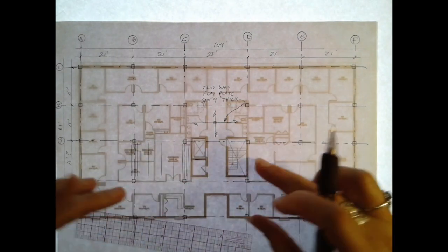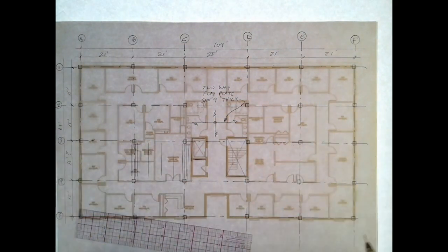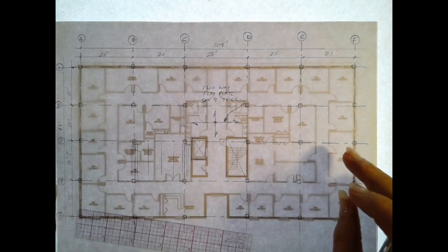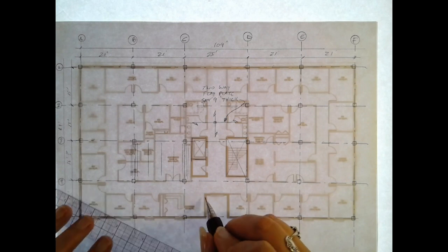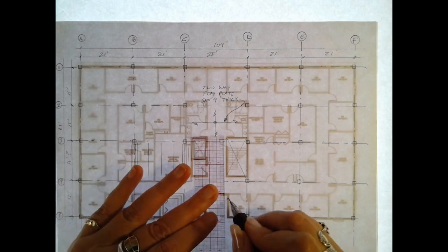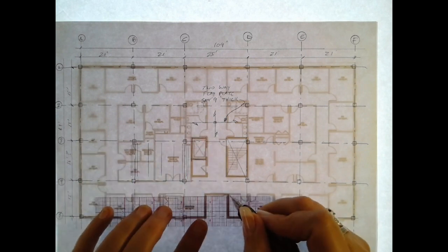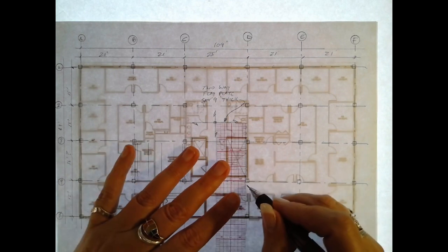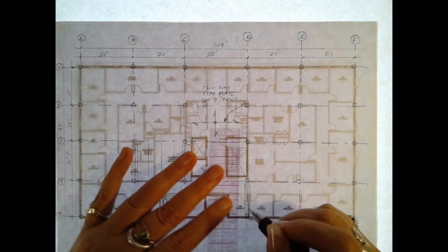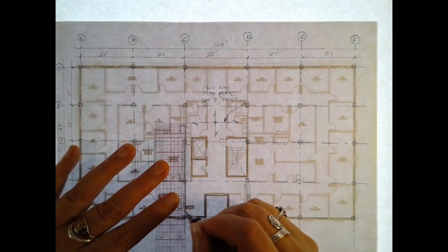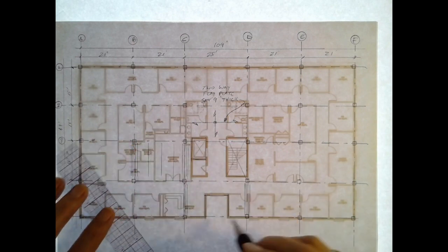So that's another consideration we need to take into account. And that really would affect this column line here. There's also a cutback in the slab here at the opening. This is relatively easy to accommodate because we would have multiple reinforcing bars right here and some right here. That forms our beam band.